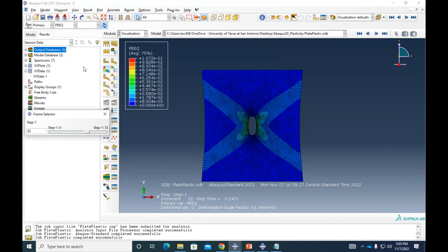All right. Or also, you are creating a combustion, right? So the gas inside your pressure vessel is at a really high temperature. Then you consider that as your ambient temperature, and then you add some convection between your inner surface and the air that is really hot inside your pressure vessel. So a lot of things that we can start adding here, but as I said, quick introduction showing a lot of capabilities, but then we're going to focus a little bit more on the things that I do, which is fracture assessment for structures, all right?